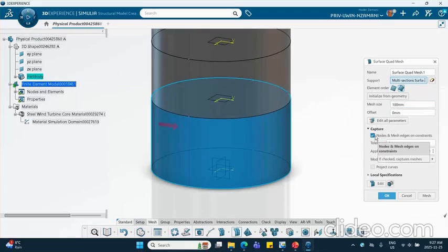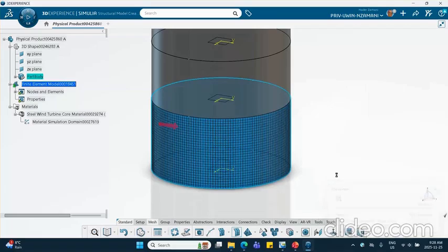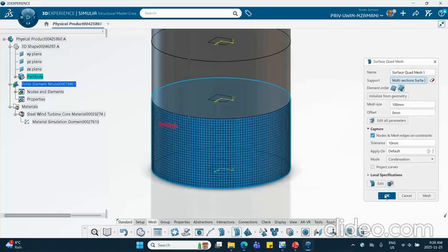And notice that this first one says also capture any nodes that you see within. I'm going to change that to 10 millimeter. It says capture any node which is within 10 millimeter of your cell. Well, there are none here. So that first one doesn't matter whether this is checked or not, but I've checked it because I knew I needed it later on. And don't forget to say mesh. See that? Mesh. Good. And then we say OK.